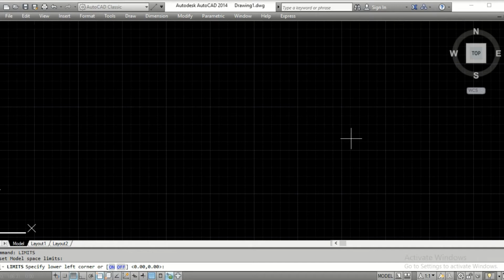You should imagine that you are actually working on the ground. So if you enter 10 meters, it is as good as 10 meters on the ground. So you are creating the drawing on the ground live. You have to worry about the sheet size only when the drawing is completed. Okay, so we'll learn that later on.